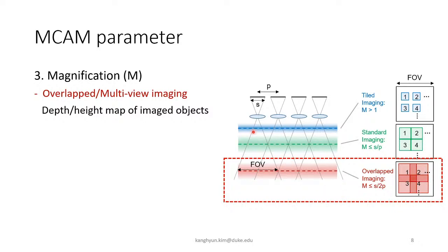Considering the specific goal of multi-view imaging, it's simple to derive the required system magnification. Each microcamera must image across double the sample plane area width P onto a sensor of width S. This sets the required magnification as this.